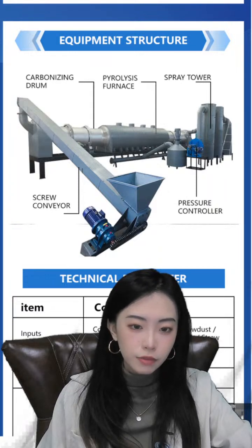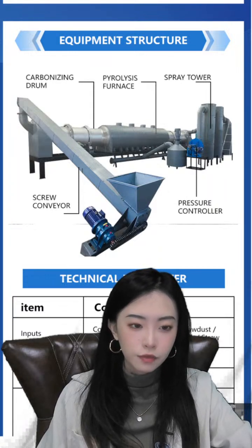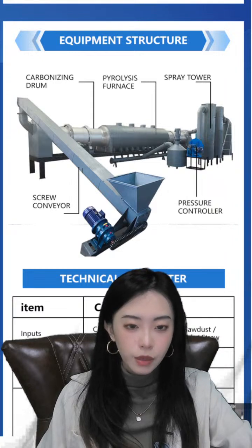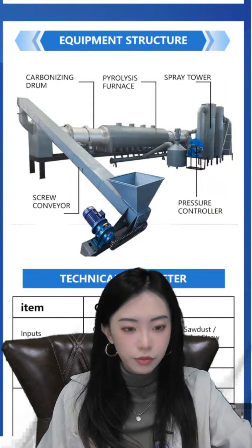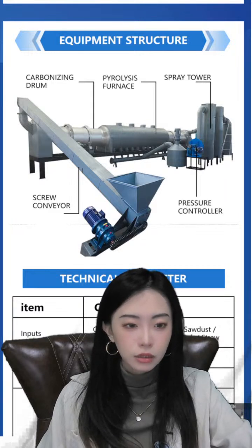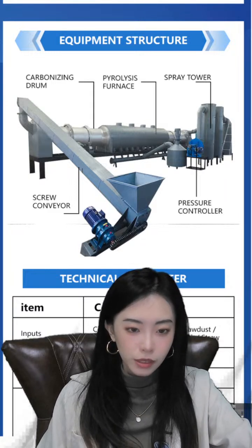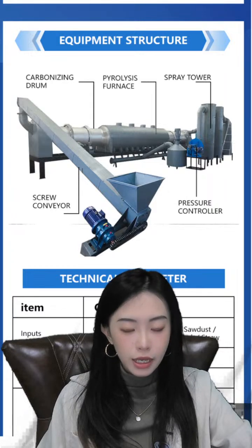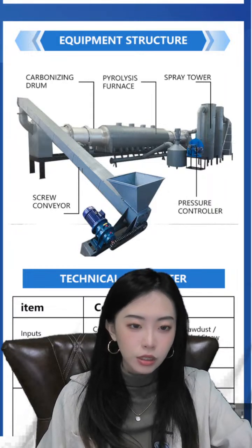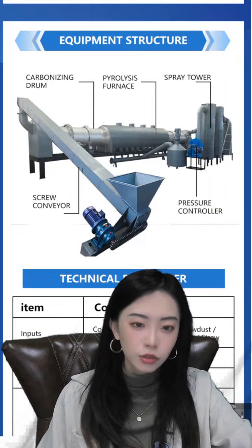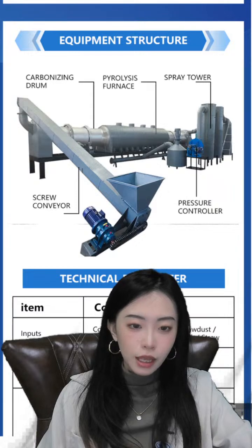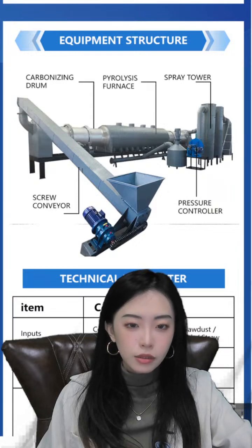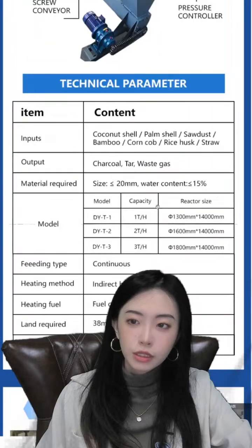In the carbonization stage, here is the furnace. The pre-treated raw materials are placed in the carbonization furnace to carry out the pyrolysis reaction at high temperature without oxygen or under a low oxygen environment. The post-treatment stage is to separate, purify, and process the charred products in order to obtain carbonization products that meet the requirements. And like this, we have three kinds of equipment.